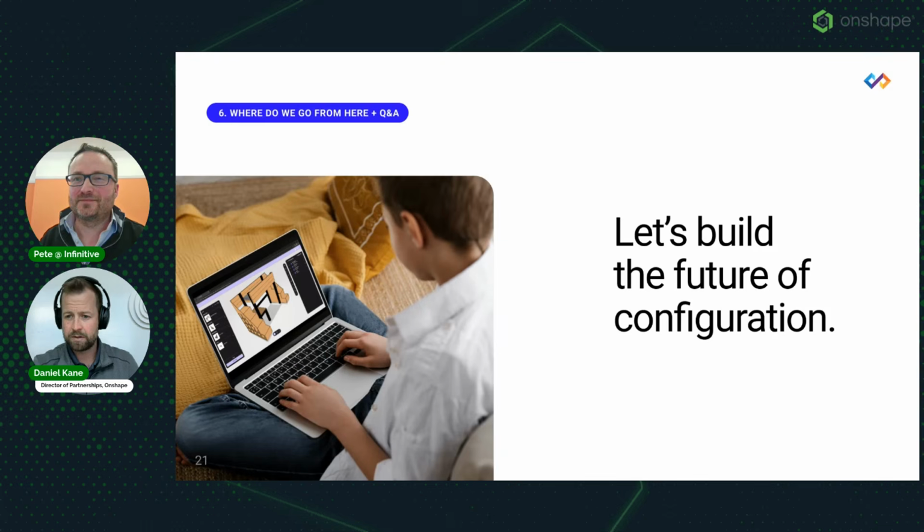Absolutely. All right. Get to maybe two more questions. So any size limitations on configurable Onshape parts and assemblies? There's a performance factor if you import a very, very large assembly. We do recommend that things are broken down and modularized. What your customer is doing is assembling a set of modules together. The more modularized the product is, the more efficient the configurator is as well, just because of the scale of CAD that's being pulled in.